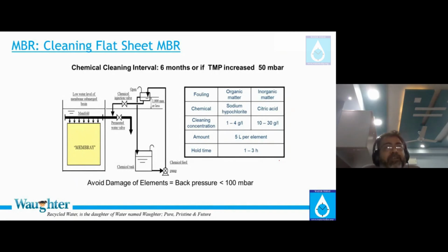In pressure filtration, you don't bother about delta P, you push the water because there's a pump to provide energy. In gravity filtration, you cannot push the water. The flow rate will come down if the delta P is higher, or if the resistance across the bed is higher, the delta P will make sure that the flow is reduced. So flat sheet membranes can be backwashed. This is the diagram. You can do the engineering accordingly. As long as you have this liquid layer, and you are pouring the water from a tank which is approximately 1 meter high.